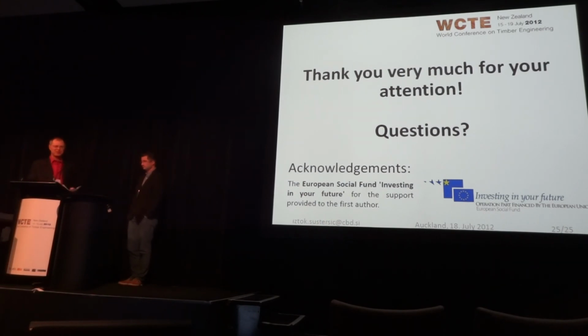Thank you very much, Iztok. It was a very interesting presentation, and it's always good to be the chairman, so I can ask the first question. We are now involved in some preliminary designs of these CLT buildings, and what we call RdRo factors, pretty much an overstrength factor in Canada and the United States. Some were saying 1.5 or 2, kind of 3. You were saying 1.6. In Canada, FPInnovations are telling us about 3. What is the number that you would use for design?